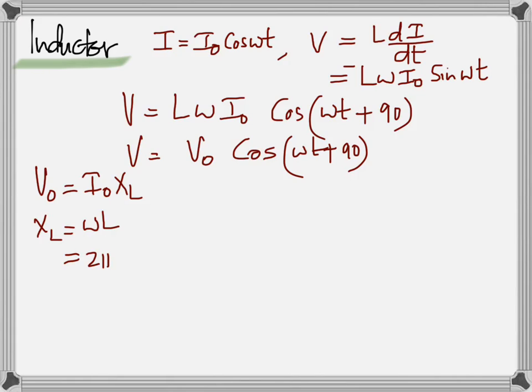Did you get what I said? Inductive reactance. Why do we call it reactance? Because watch. That's why I said this is very important. Watch this again. V naught is I naught times what? Actually, omega times L, isn't it? So you know that my XL here is omega times the inductance. That's what I call inductive reactance. And omega, you know, is 2 pi f. Right? The f is the frequency. So finally, XL is going to be 2 pi times the frequency times the inductance,